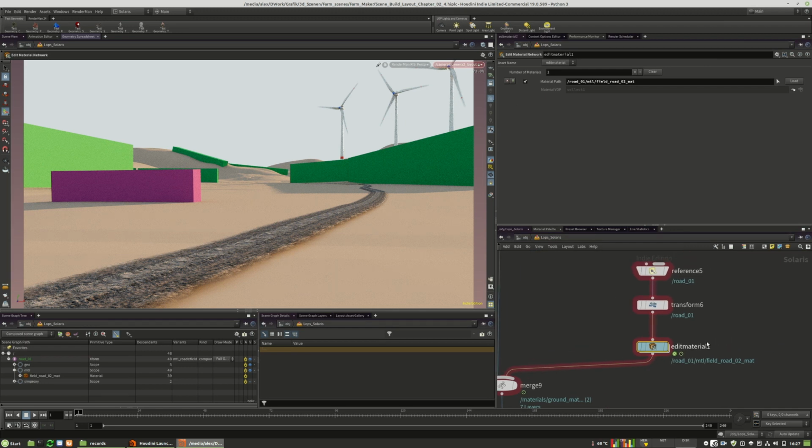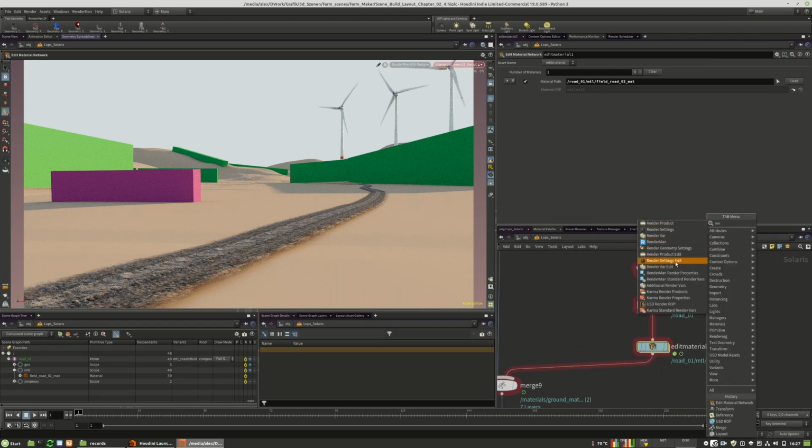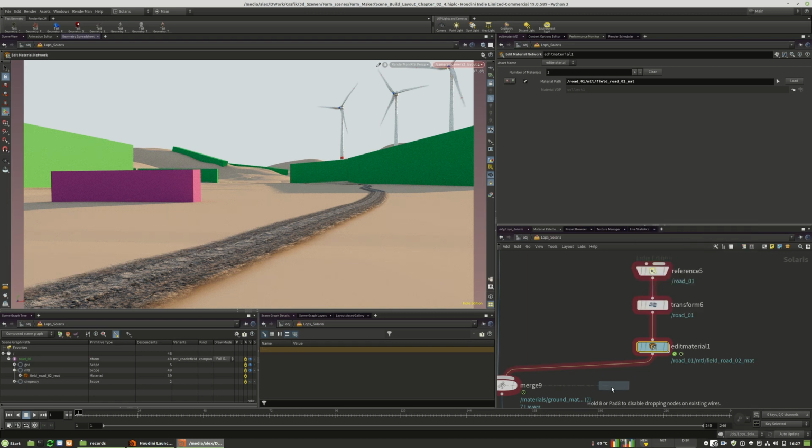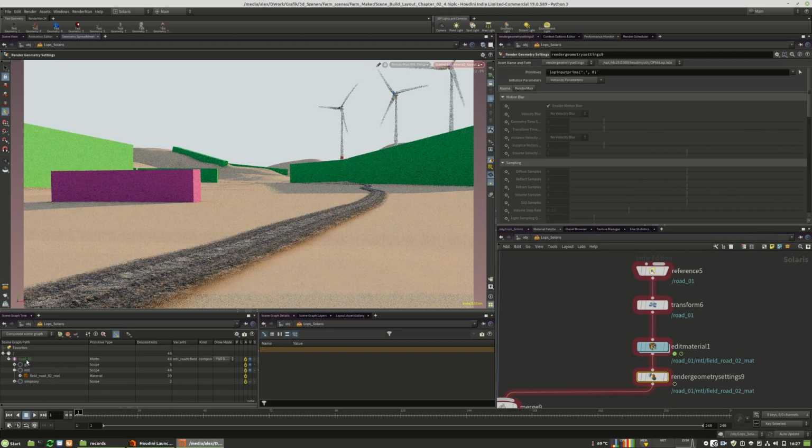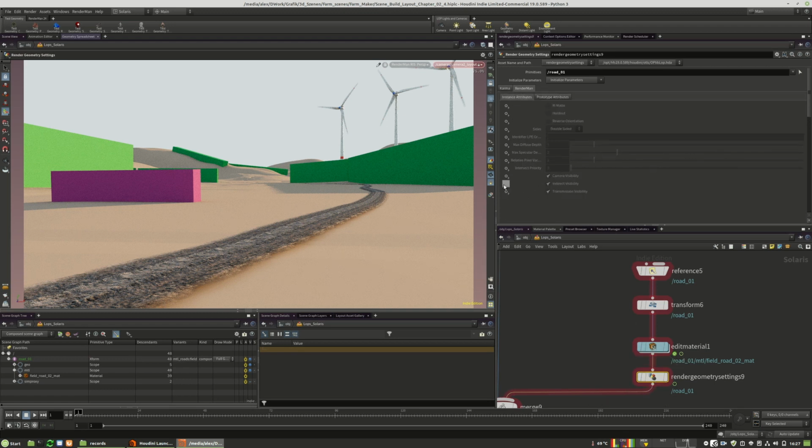What happens if I would deactivate the shadow dropping of this road? It's maybe not that accurate, but just in case, it will resolve a lot of the issues. Since we are not building a physical thing, we can cheat a little bit. I will drag and drop the road right in here, and I will deactivate the transmission. What happens? It will blend a lot better into the scene. So it's not generating shadows anymore. This has the disadvantage that it will not cast shadows on themselves.